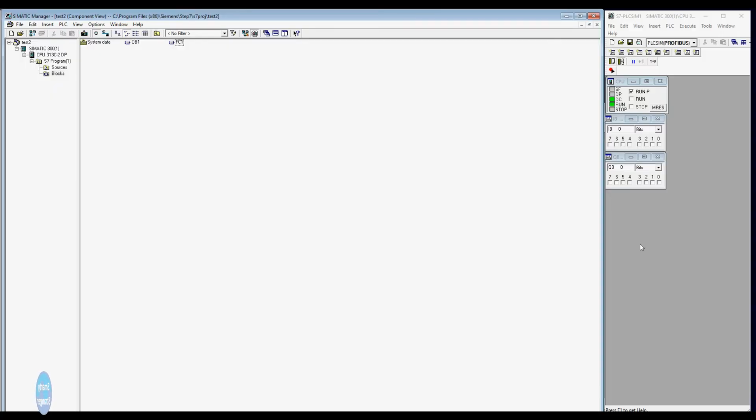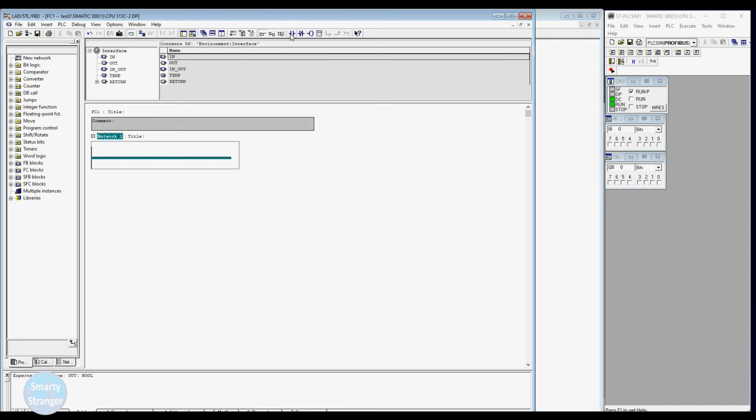Now we will convert it into a ladder diagram. In our example we have a switch and we want to control the lamp. So, we need an input and an output. First, we place a normally open contact in a rung, and then place a coil. Give a tag to the contact and coil. For making a tag, we require a physical address and a name.